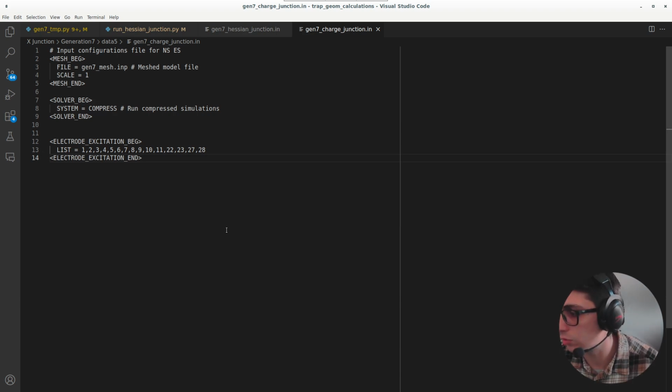But the actual usage we make of that is that we first solve for the surface charge distribution. We first solve the electrostatic equation to get the distribution of charge on the mesh elements, and then after that, in a separate simulation, we evaluate the potentials where we want in the 3D space.